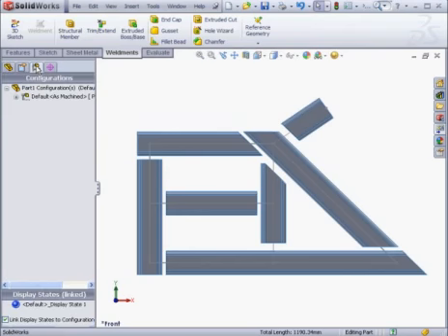Let's go to the Configurations tab now. As you see here, we've got two configurations, as machined and as welded. What this means is that we can create the part as machined, for example, creating drilled holes on one side of the part, etc. However, when we switch to the as welded configuration, those holes are going to be suppressed. What we see automatically is the part as appropriate for a welded configuration. Of course, the more complex your part, the handier this feature is.